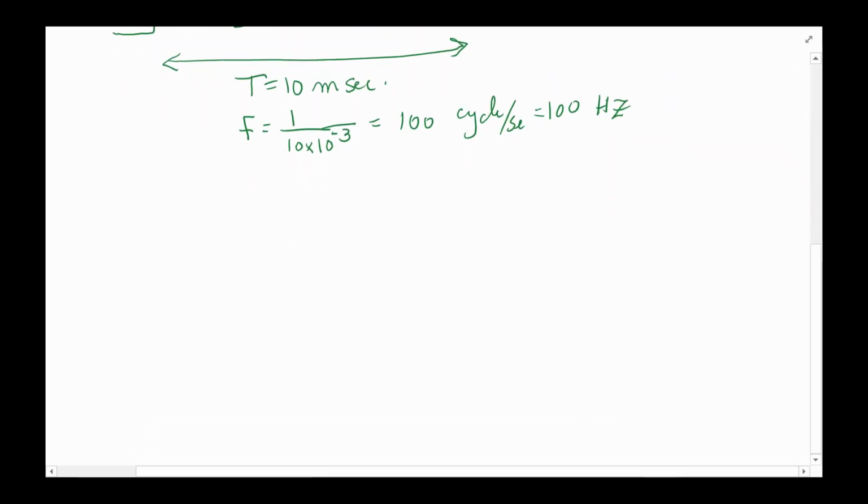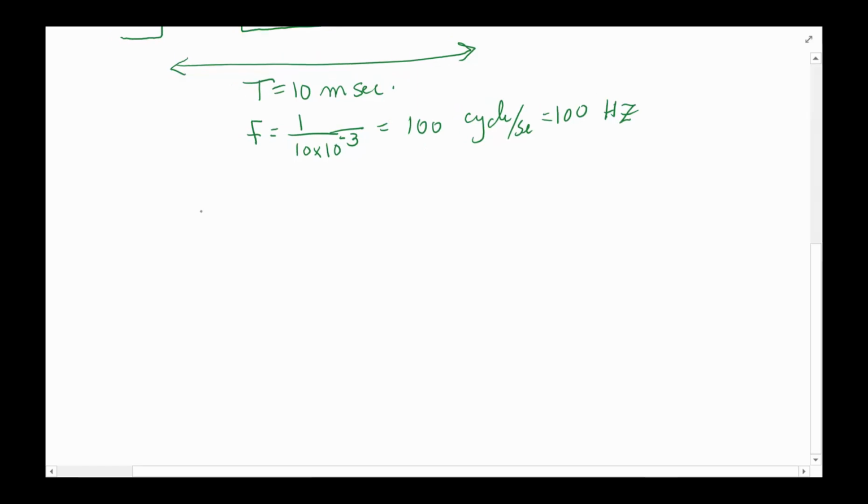For example, if you're talking about a light, once the frequency goes above about 30 hertz, 30 times per second, the human eye will integrate it together, and you see as if the light is on all the time, except a little dimmer. And as you increase the duty cycle, it gets brighter. So as long as your frequency is above that, your eye will integrate it in time.